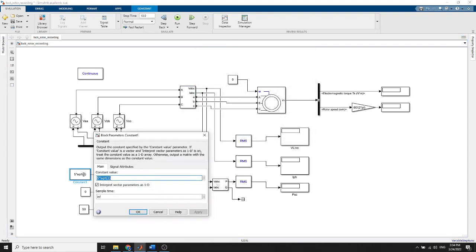And over here, we must make sure that the output is 400. So in order to get 400 in the output, for the input source we must do 400 times the square root of 2, because here they will divide again by square root 2.